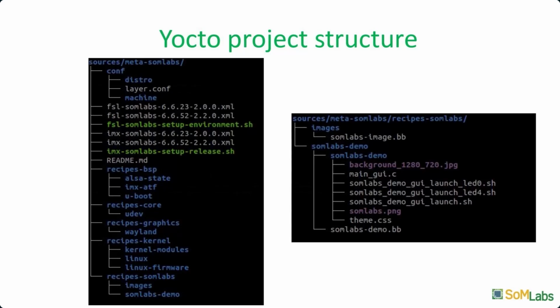And we have also a machine directory with machine files. Each hardware platform that we build the Yocto project for has its own configuration file, like Titan SBC, as in our example, describing the target hardware platform, the architecture and hardware components, and this configuration file is used later to create the distribution.